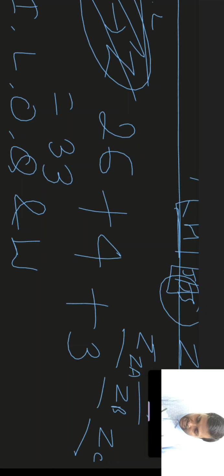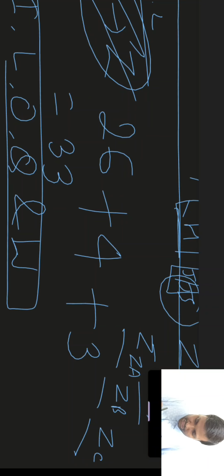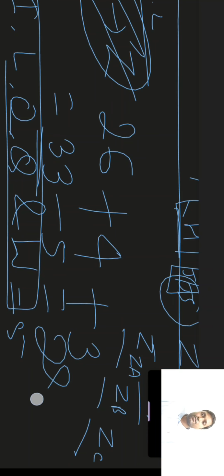So we will eliminate these from this 33 count. These are 5 in number. So 33 minus 5, there are altogether 28 fundamental deviations. So there are altogether 28 types of fundamental deviation for hole. Similarly, there are also 28 types of fundamental deviation for shaft.